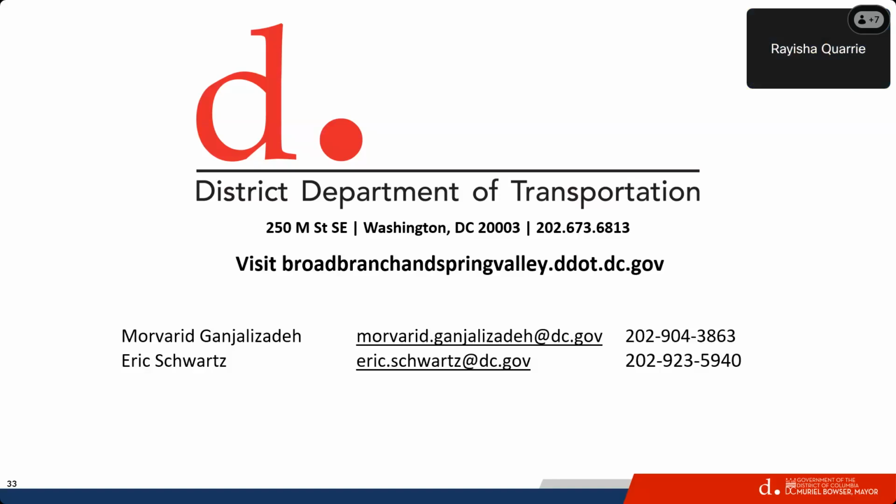Did you guys answer this one? Does DDOT believe in having one pedestrian break in a 100? Based on the design engineering manual, the DDOT standards, the pedestrian break cannot be more than 70 feet. So if we have like 140, then we have two pedestrian breaks. If it's 105, based on the design standards, one is enough. And I'm going to come talk to you. If you think you need two, I can provide two. Okay, great. And I think it's great that you guys are going out to meet with them. That's awesome. So hopefully a lot more of your questions and concerns can be answered then.